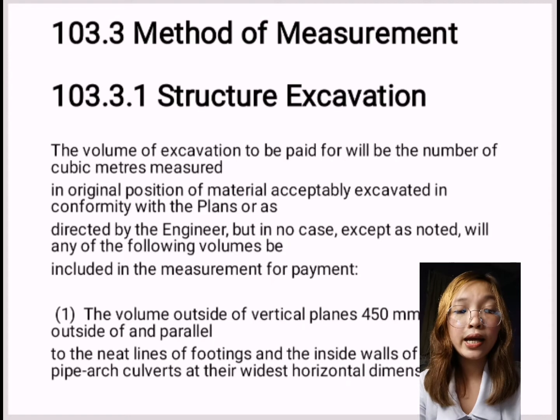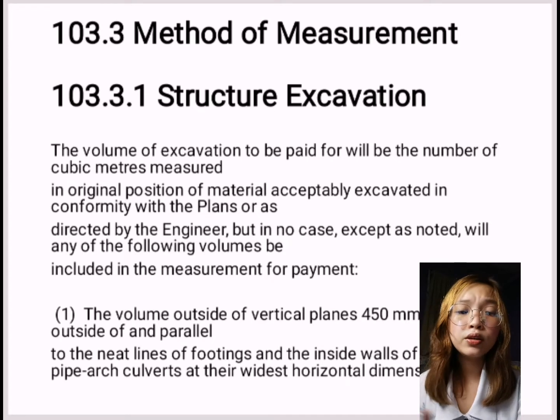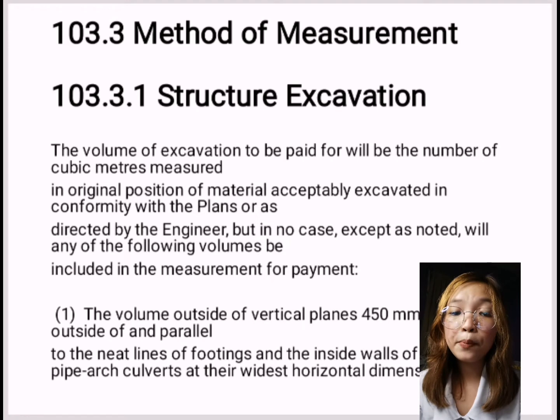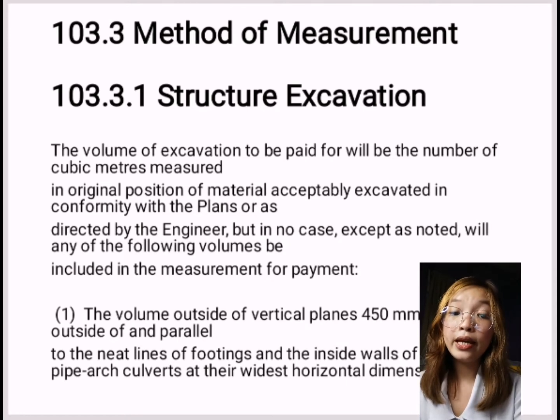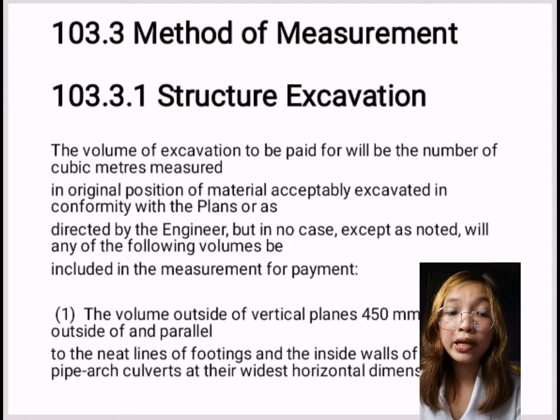Under this is the item 103.3.1, which is the structure excavation. So the volume of excavation to be paid for will be the number of cubic meters measured in original position of materials acceptably excavated in conformity with the plans or as directed by the engineer.